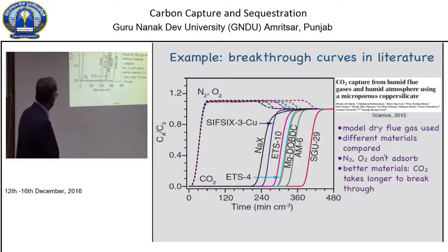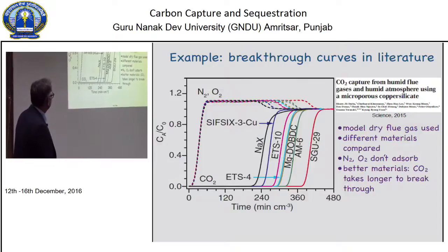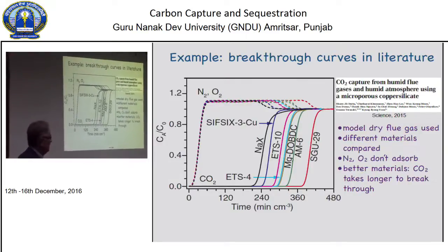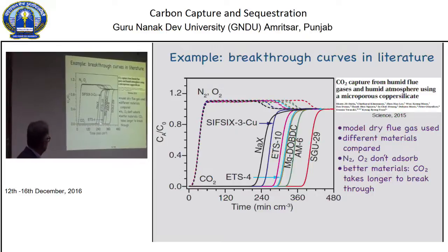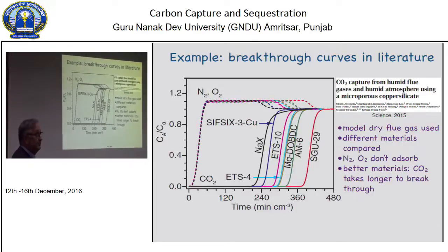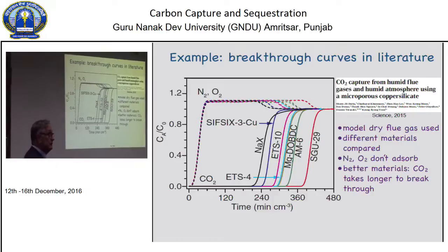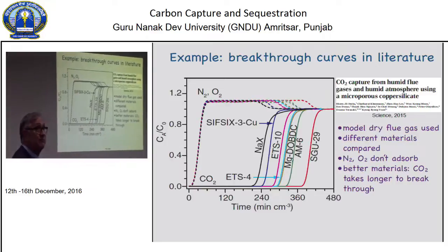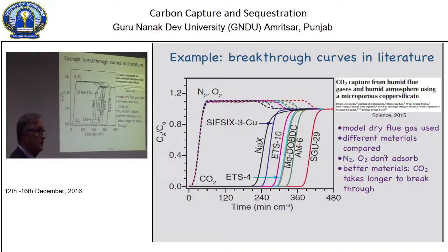And you notice from 0 to about 200 seconds, the sodium X zeolite is adsorbing all the CO2, and then there's the beginning of the breakthrough curve. If you look at these various materials, you'll recognize that this particular powder has the most capacity to adsorb CO2 because the time for breakthrough happens to be the latest. So this is how you will see in the literature a lot of adsorption processes characterized, not in terms of Henry's law, but in terms of breakthrough curves. They're relatively easy to measure.